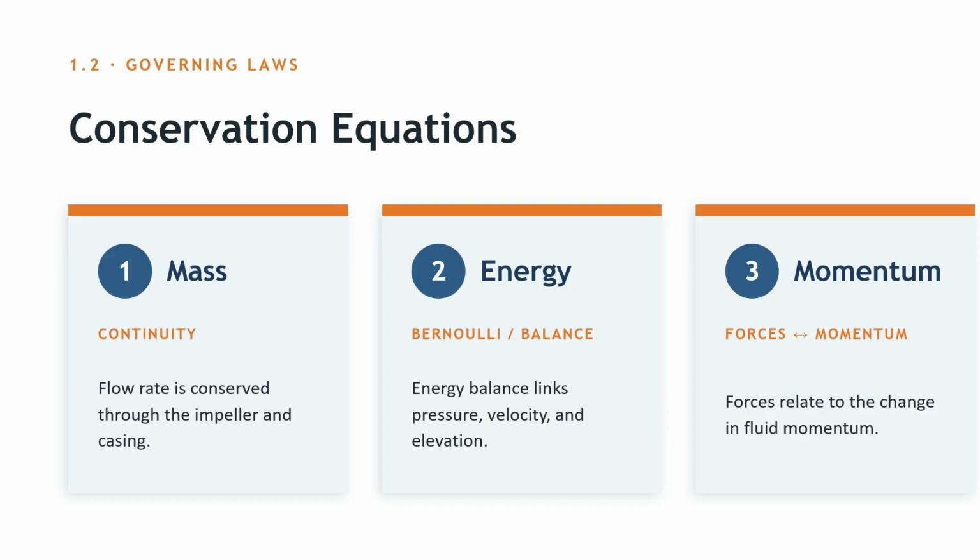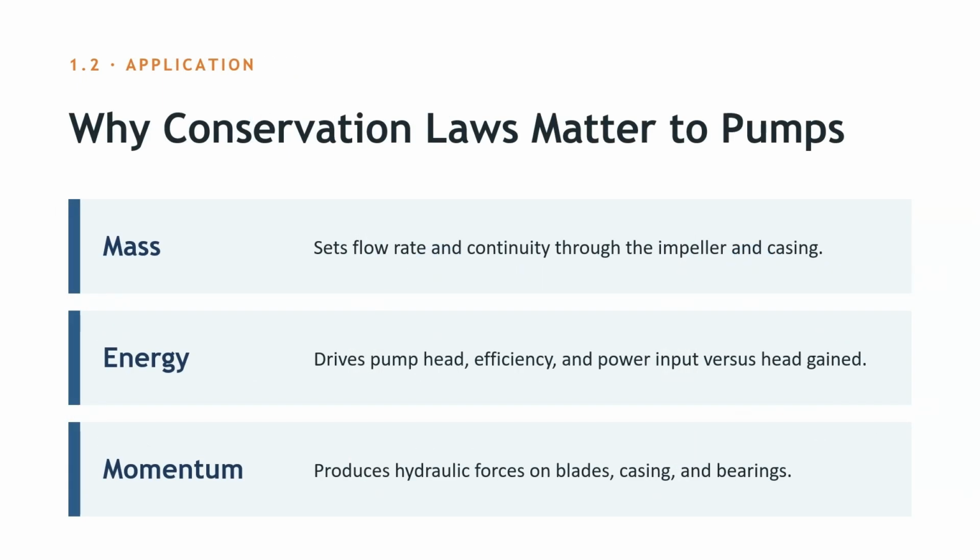Conservation of momentum links forces to changes in fluid momentum. Hydraulic forces on blades, the thrust on the casing, and many vibration problems all trace back to momentum balance. Every time we say this pump develops this much head, or these are the hydraulic forces on the impeller, we're using these conservation laws, often without mentioning them explicitly.